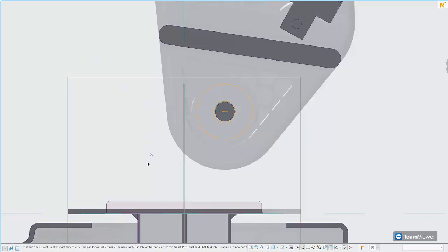Again, when creating this line, I might want it to reference the top of this plate. It's currently not a reference. Just by hovering over it, the software presents it to me as a reference for me to work with, and this has added it to the references table within the software. You can see as I'm working also that it's presenting me with the tangent notification so I can snap to how I want it to be.